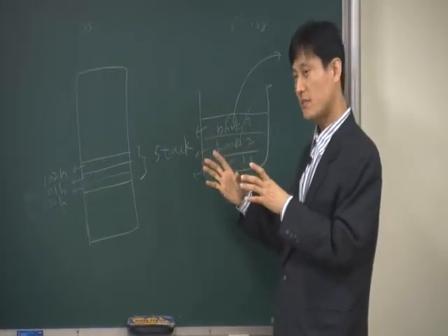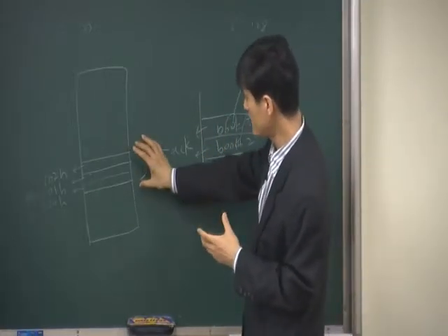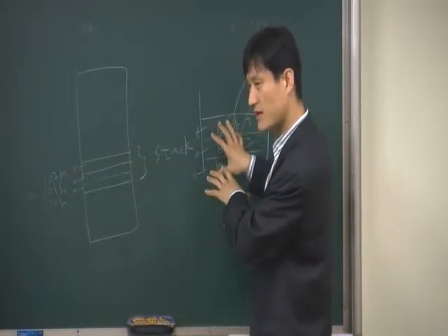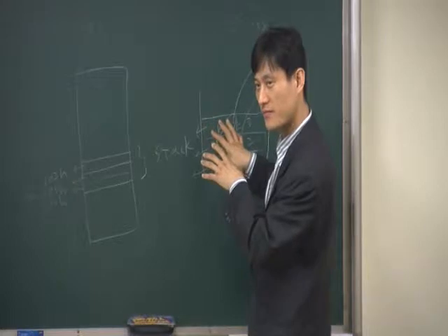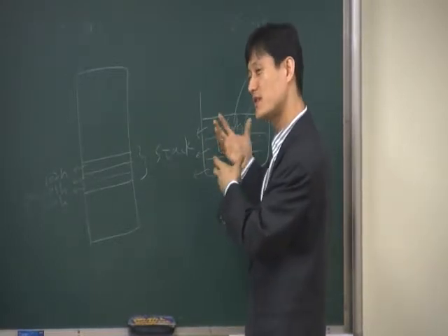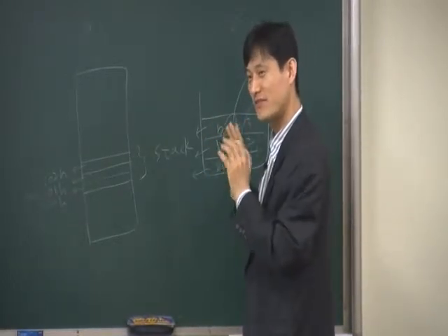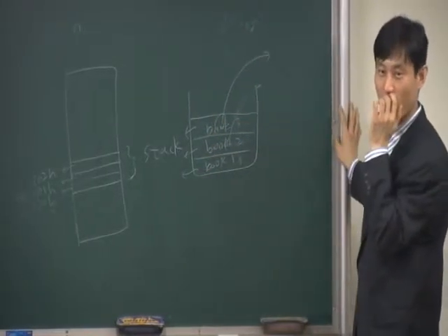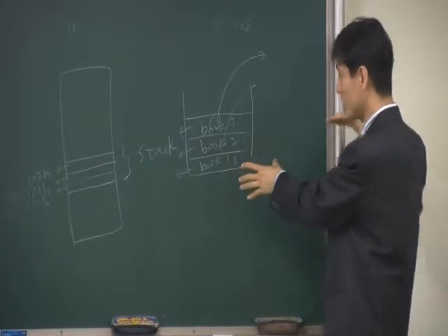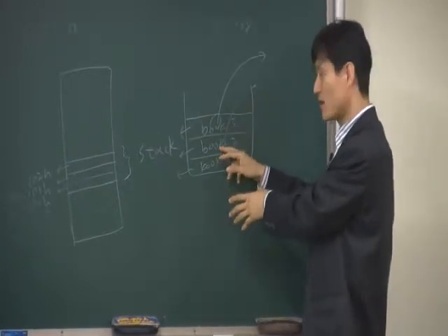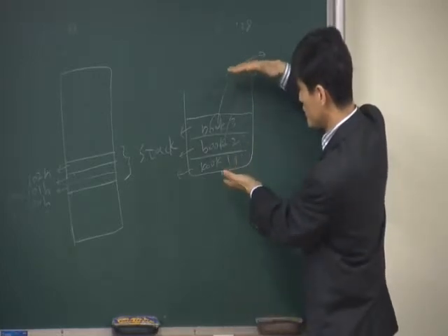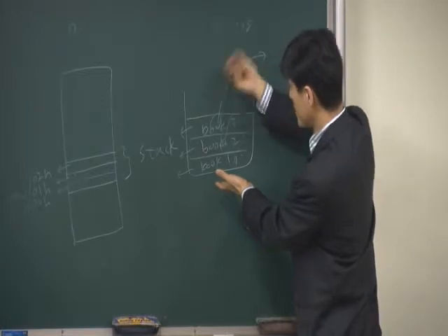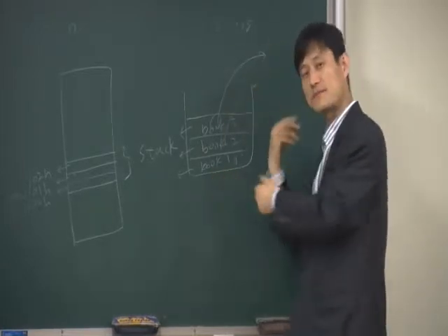physically it's the same address, but we declare that this memory is a stack, and for a stack we use it this way, like a last input, first output. This is the way of using a stack. It's not physically different, it's the same memory, but we are going to use it this way. We are not going to directly access a certain memory. What we do is put values on one after another, and bring them out one by one.